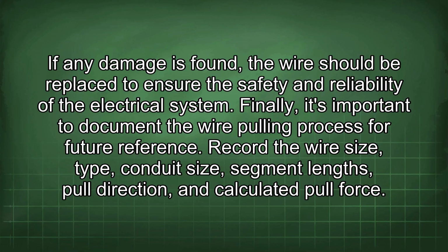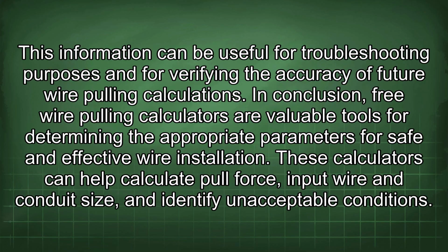Finally, it's important to document the wire pulling process for future reference. Record the wire size, type, conduit size, segment lengths, pull direction, and calculated pull force. This information can be useful for troubleshooting purposes and for verifying the accuracy of future wire pulling calculations.